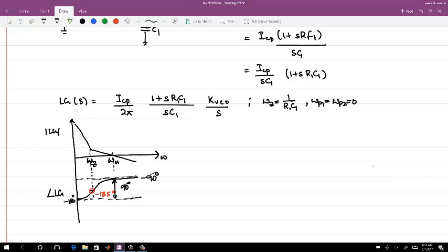So does that answer your question, that the VCO as an integrator is something separate? An additional integrator you need only if you want frequency error information. If I say the frequencies are the same and I just need a phase lock, I will not go for this integrator at all.